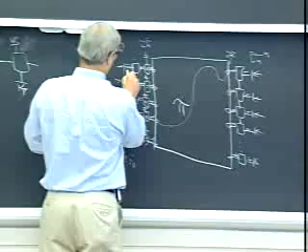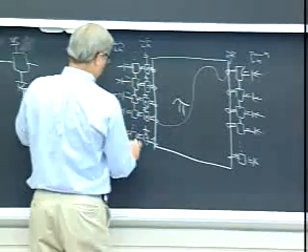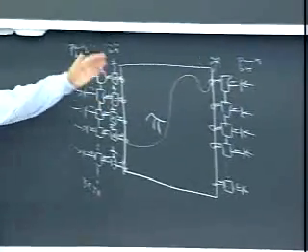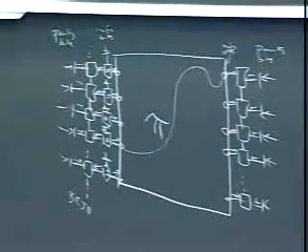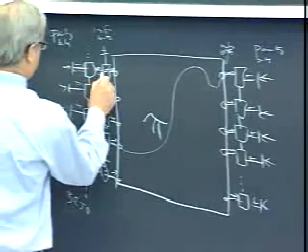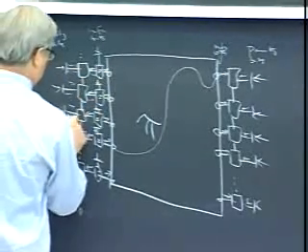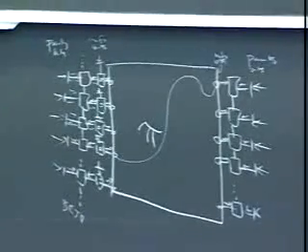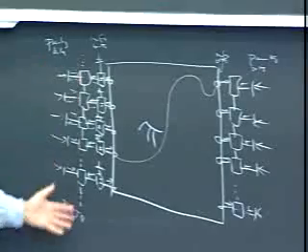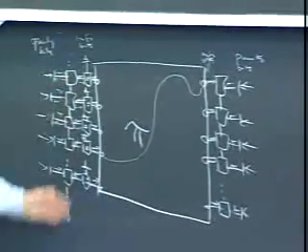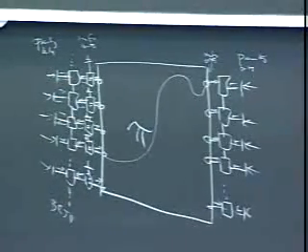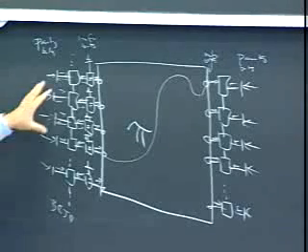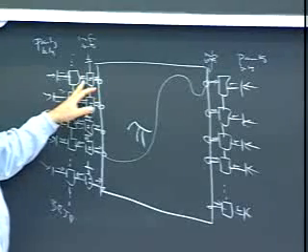Given all these messages, we do our backward-forward algorithm, alphas and betas, eventually epsilons, extrinsic information coming out on all nodes there, and so forth. That requires going up and down the whole trellis. If this is a 1,000-bit block, as it often is, or larger, it means going from top to bottom through the whole block and doing one sweep of a BCJR algorithm through that block, which will generate a bunch of extrinsic information over here.